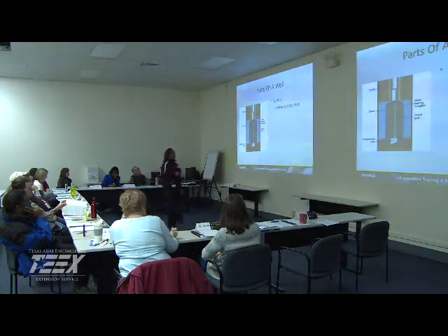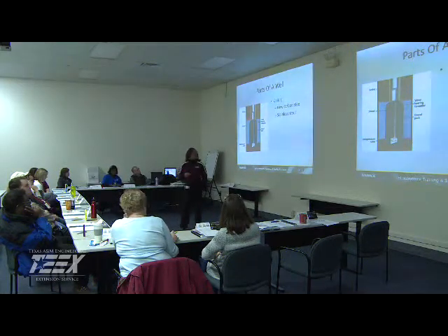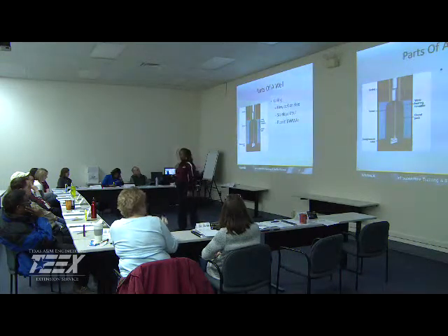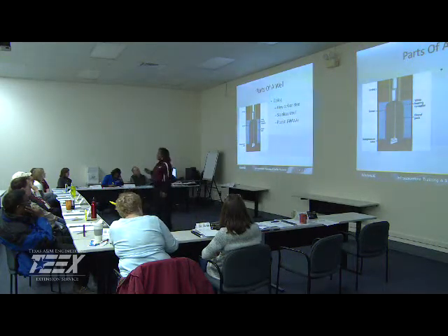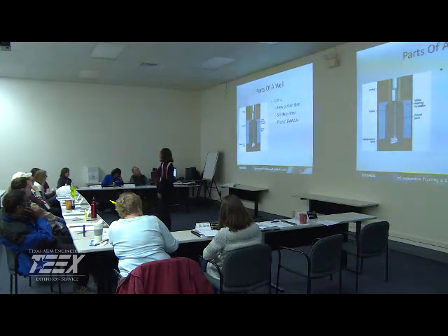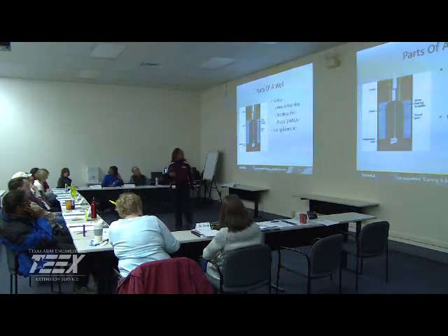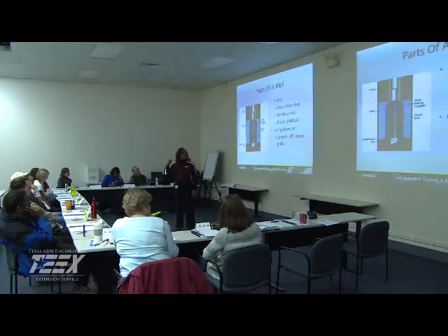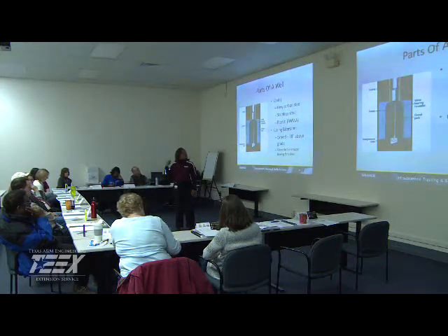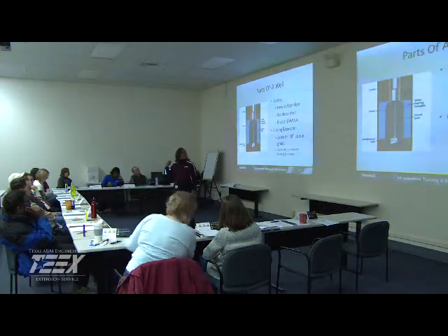Parts of a well, we have the casing, can be new carbon steel, stainless steel, or PVC. You want to make sure that if you're using plastic, that it adheres to AWWA specification, American Water Works. Do you all also use their standards for a lot of things? Okay, cool. The casing should extend at least 18 inches above the natural elevation, and it's going to also extend down into the top of the water-bearing formation.